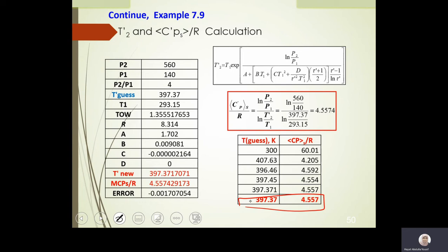Now, again, with the pump, there is efficiency. The equation of the pump for the efficiency is delta HS over delta H. But delta HS means that you have to consider an isentropic process, right? And then here we have a problem. Normally, with the pump, the inlet to the pump is liquid, and if I compress it more, the outlet is going to be compressed liquid.